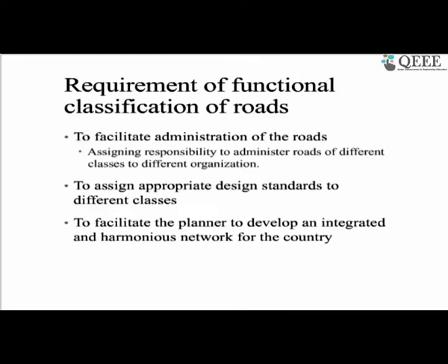And now the other question I also got is, how are national highways and expressways differentiated? The expressway, if you look into it, is more like a freeway where access is totally controlled. It means there won't be a lot of intersections or interchanges in the rural expressways. Whereas on national highways you may see intersections and more access, and the national highway speed is like 80 kmph, whereas the expressway speed can be up to 100 kmph.